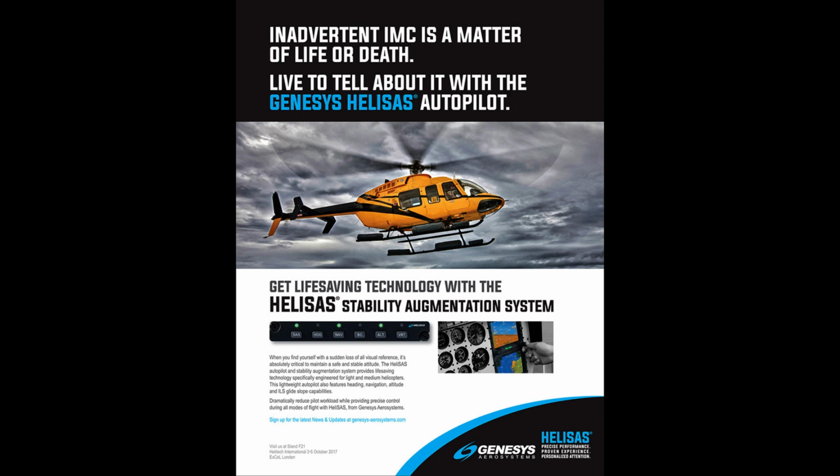This computer receives data input from the flight instruments for attitude reference and from the navigation equipment for navigation and tracking reference. An autopilot has a control panel in the cockpit that allows the pilot to select the desired functions, as well as engage the autopilot. For safety purposes, an automatic disengagement feature is usually included, which automatically disconnects the autopilot in heavy turbulence or when extreme flight attitudes are reached.